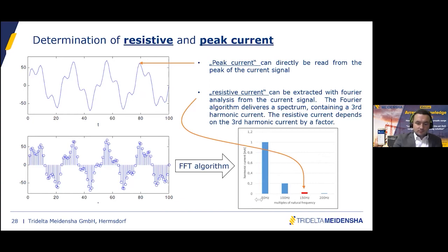And yes, this has to be highlighted, because during the smartCOUNT development, we had many utilities all around the world offering us to access their accounts and to see their smartCOUNTs working with their surge arresters. And it has turned out to be very successful, because many old surge arresters have been found suspicious and exchanged against new surge arresters to prevent them from failing preemptively.